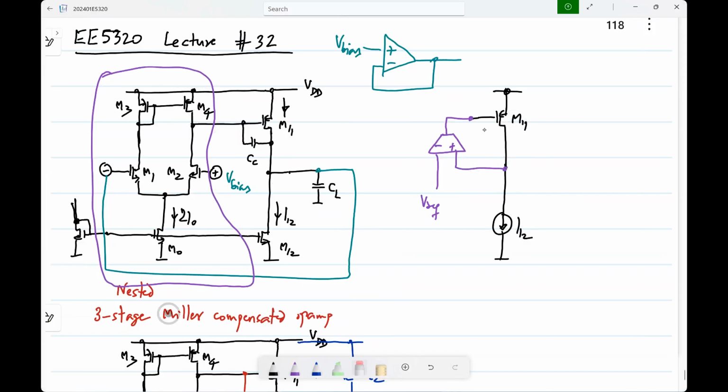Of course, that's not the point of this. There is an op amp here, but just from the point of view of biasing M11, the rest of the circuit is there to provide negative feedback. So once the op amp is in negative feedback, all the stages will be in DC negative feedback and each one will get biased correctly. Okay. The same goes for M4 and so on.